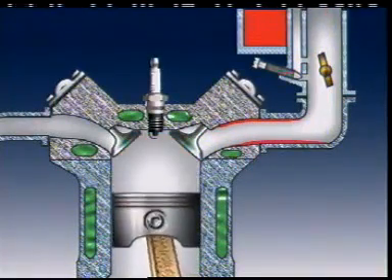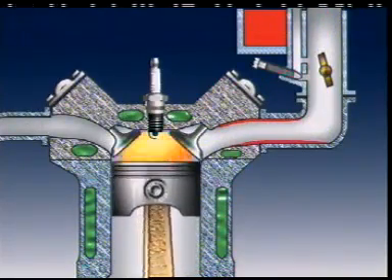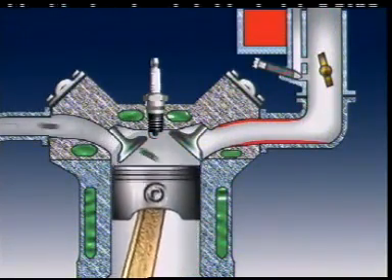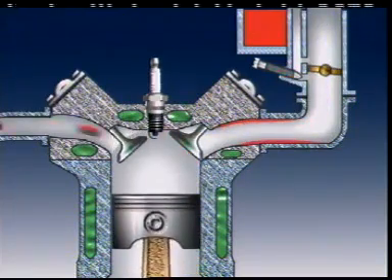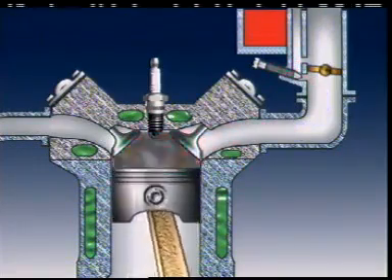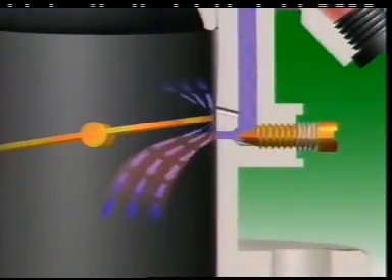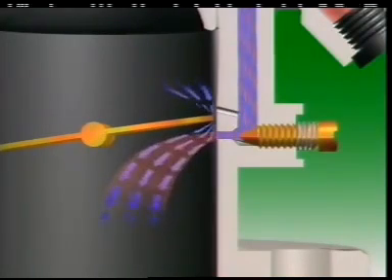Changes in operating conditions can change mixture conditions within the manifold. If a carbureted engine is being driven at moderate speed and the throttle is suddenly closed, any fuel condensed on the manifold walls is drawn into the cylinders. The low pressure in the manifold also acts on the idle circuit in the carburetor to cause a larger amount of fuel to flow from the idle discharge port.